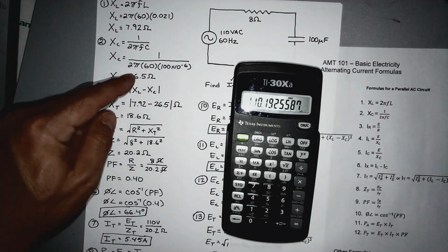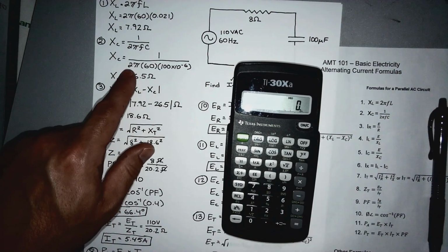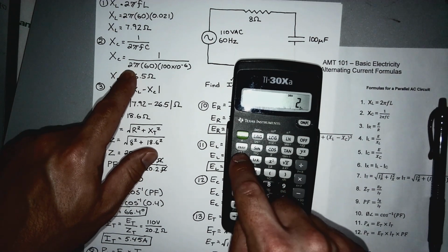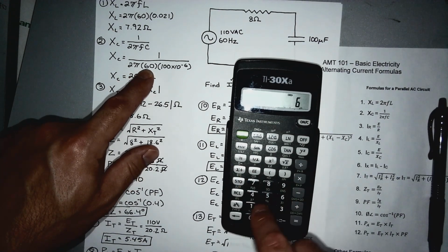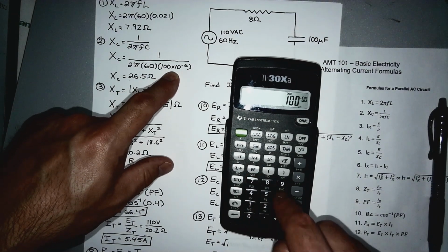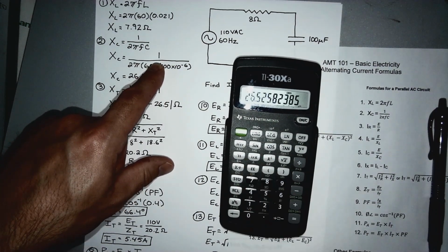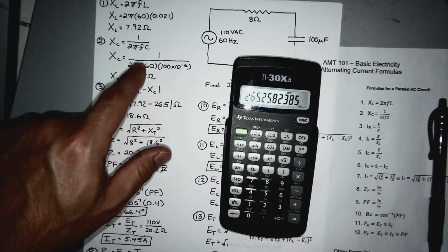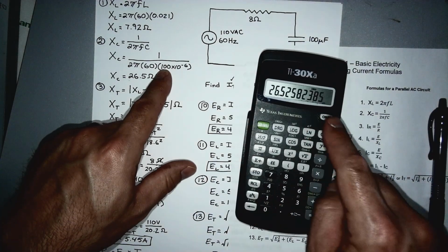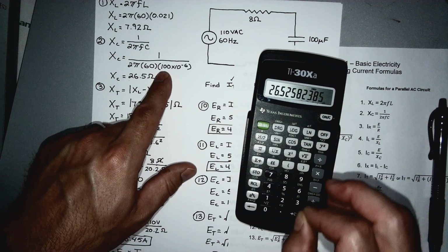If you write everything out, this will keep track. You can actually go, okay, one hand's here and one hand's on my calculator. So I'm going to say 2 times pi times 60 times 10 to the negative 6 equals, and that's everything under the bottom, and I still have to take the reciprocal, so hit the reciprocal, and that comes out to be there. If I keep a finger over here, keeping track of what I'm supposed to be putting in, and use my other finger to punch the keys in, I'm more likely to not make a mistake.